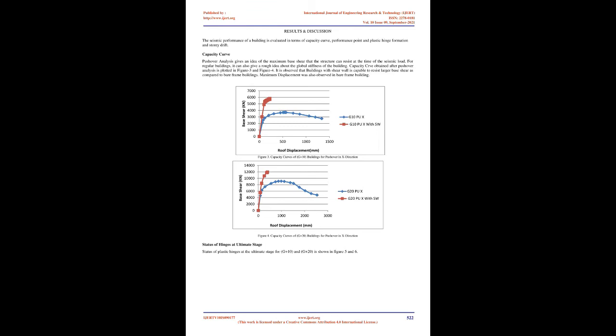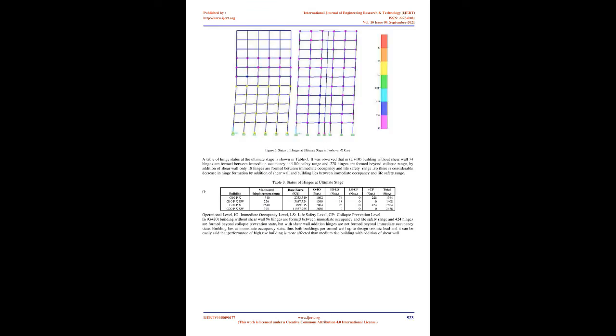Figure 2. Plan of building. Story height for the ground floor is kept as 3.5 m and typical story height is kept uniform for all stories, i.e. 3 m. Slab thickness is kept 125 mm for all floors. Shear wall is modeled as a mid-pier frame element. Thickness of shear wall is taken equal to 200 mm.